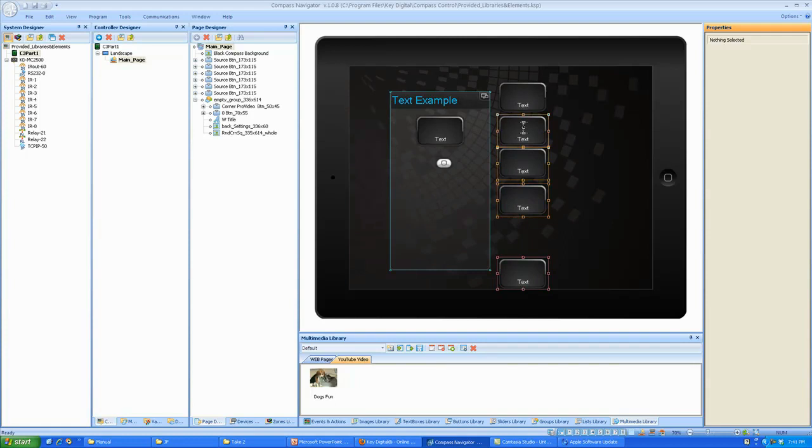So let's select one more item which wasn't previously selected, and now my two reference points should adjust. Yeah, there you go. Sure enough, we have pink on the topmost and bottommost elements and yellow on everything in between, and we just go ahead and double click, and that spacing will automatically take place for us. There we go.